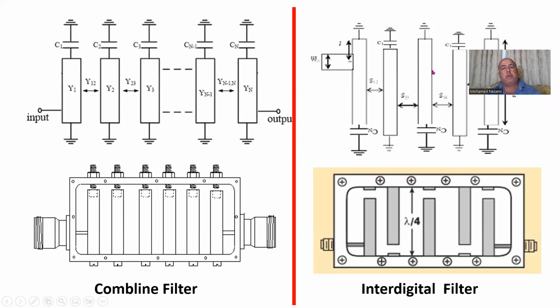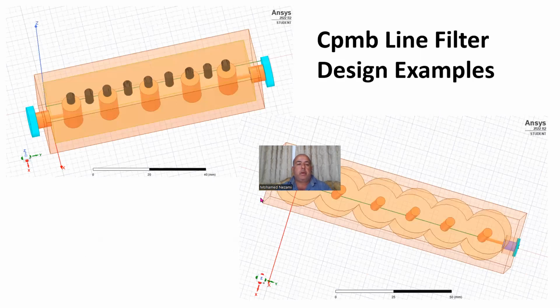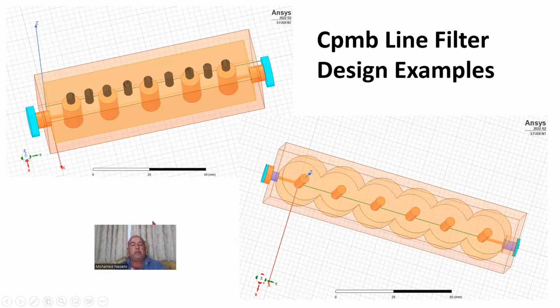Today, just to refresh your memory, we are covering the design and construction of the comb line and the interdigital filter, and both have quarter wave resonators, tuned via an end capacitance using screws. Now, the design of these filters is basically done in HFSS, at least on my end, but it can be done with CST or any other European packages.